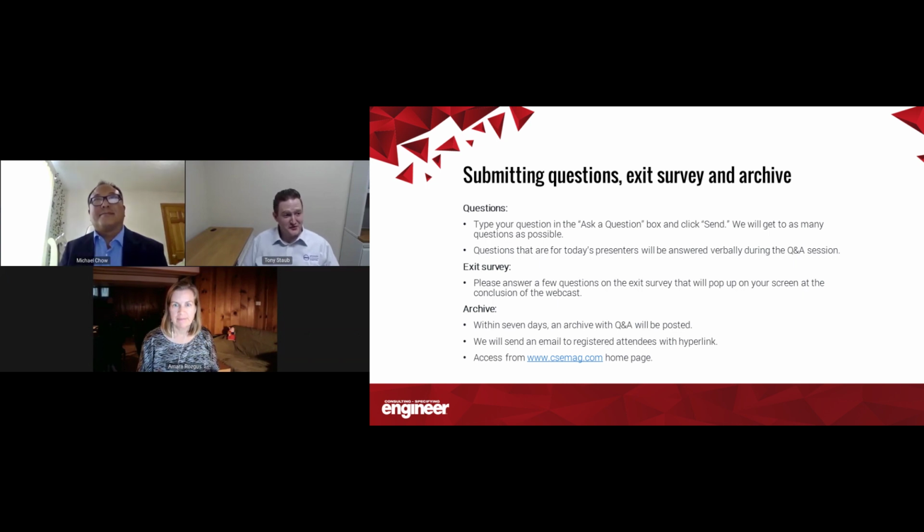That is a very good question. So it's up to me to decide when I'm designing, I will typically go with 4,000 Kelvin. And here is my reasoning for that. The way that the human eye perceives light is that a higher color temperature, that more blue, is perceived as a brighter space. So there is a theoretical benefit to having higher color temperatures because you can perceive that as a higher brightness.